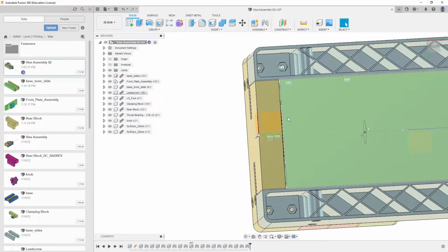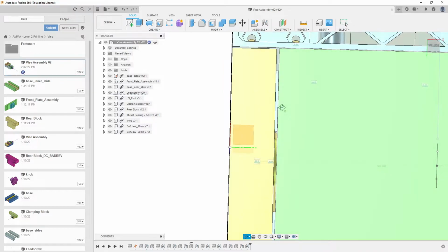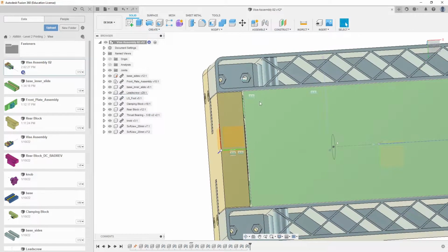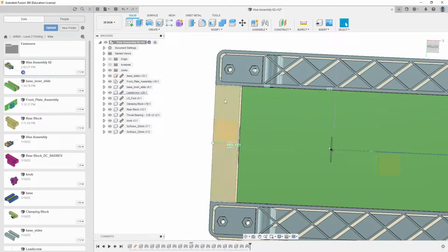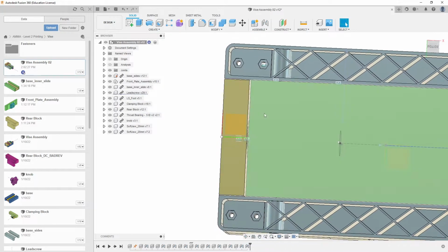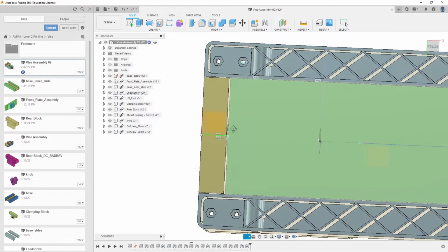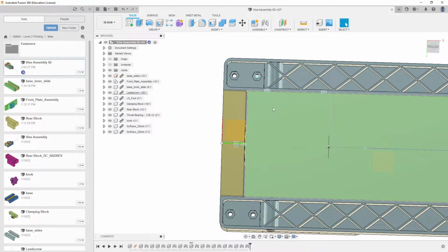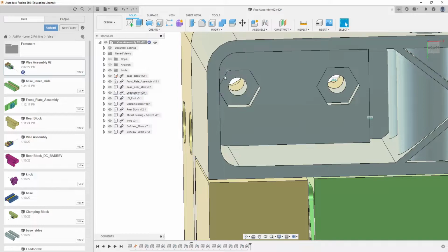Now over here, you can probably already see that there is a fairly substantial air gap. I can tell you that that is only 1 millimeter. That's a 1 millimeter gap. This is because if for some reason there is an issue with this, that this is hitting this, and because of maybe a bump or something like that, it probably won't fit these holes correctly. You could maybe get it to work, as in you could shove it in there, but problems all around. We want these fasteners to go through these holes pretty nicely, and as you see, we've got these recessed nuts right in here.